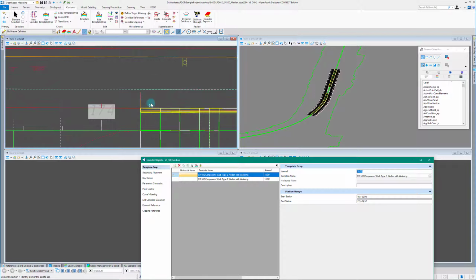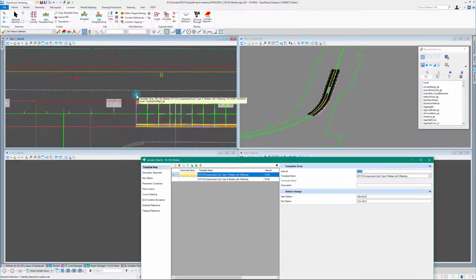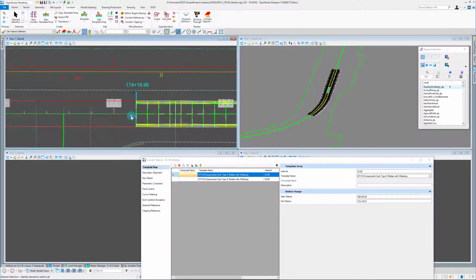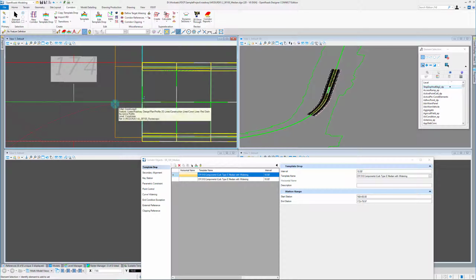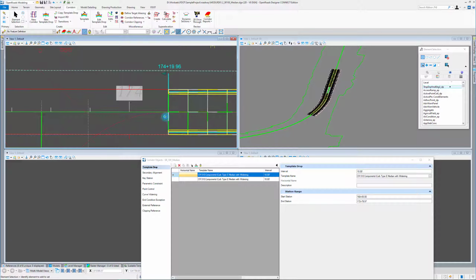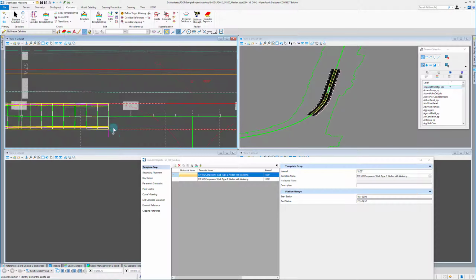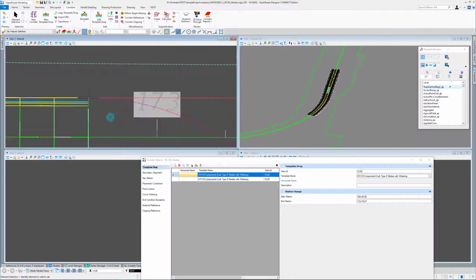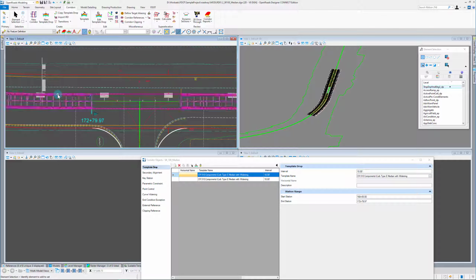And what I want to do here, just to make sure that the ends of these template drops still remain ruled, because right now they're not ruled to that end of that control radii, I'm just going to grab the end and snap there. Now you can see I got a rule. Same thing with this one. Snap, it's ruled. And that's it.